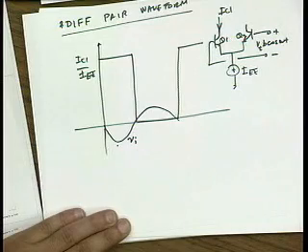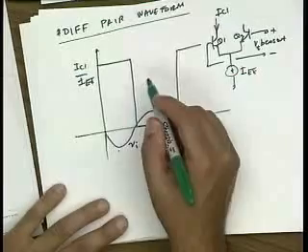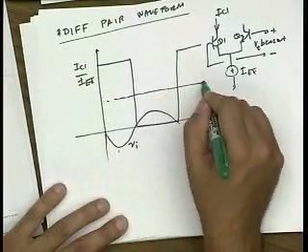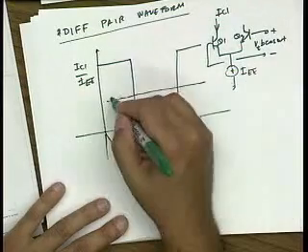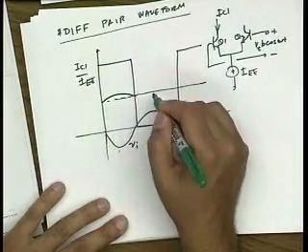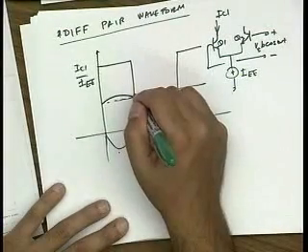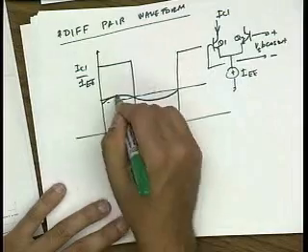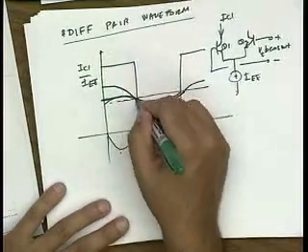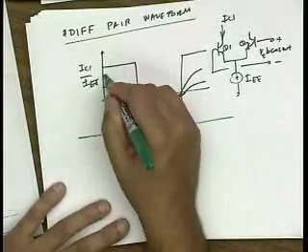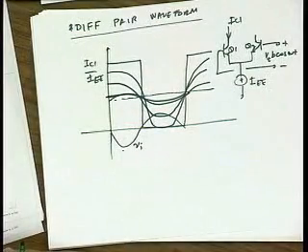And as you could imagine, as you lower the input voltage, if you make it very small, then the average current through here is basically IEE over 2, and it would be a sinusoidal kind of signal. And as you increase the amplitude more and more, actually, sorry, this is a bad drawing. Looks like this. As I increase the amplitude more and more, it would tend to approach the square wave in the limit. Okay?